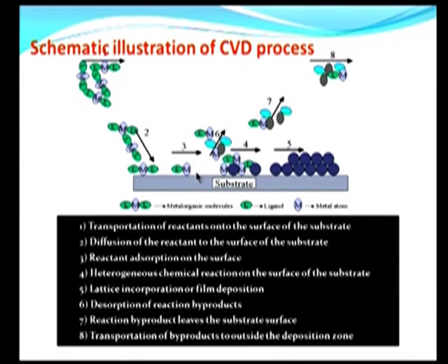If the substrate temperature is not high enough to allow the reaction to take place, of course, then there is no nucleation. But usually these reactions take place over a range of temperatures, and therefore, it would be possible to lower the temperature in order to get smaller crystals that are generated out of this heterogeneous nucleation process.